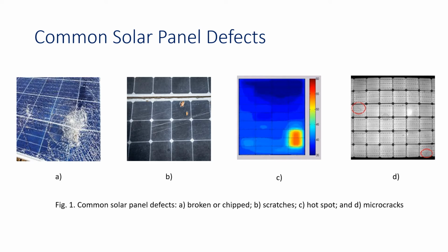Moreover, scratches are solar panel defects too, as shown in Figure 1, letter B. They may hold dirt and moisture which can penetrate and cause damage to the cells. The scratches in encapsulation seem to have a minimal effect on the solar cell, but they minimize the power production of the solar panel. Hotspot occurrences should be avoided in any photovoltaic installation of solar cell.